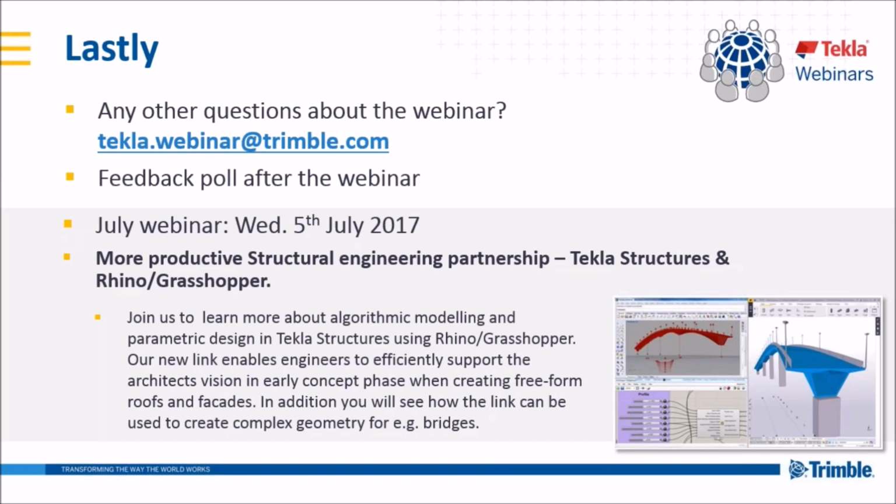That means if you use Tekla Structural Designer, you get all the load combinations for the frames, for the whole structure, and then you take all these forces and apply them to the joint. If we have this information, Idea StatiCa calculates everything correctly, guaranteed, but it's the responsibility of the engineer to get the proper loading in the global analysis.